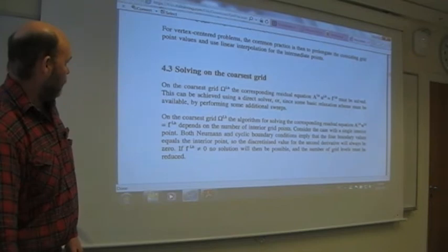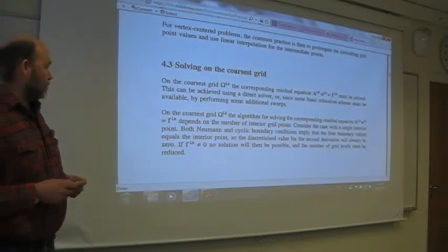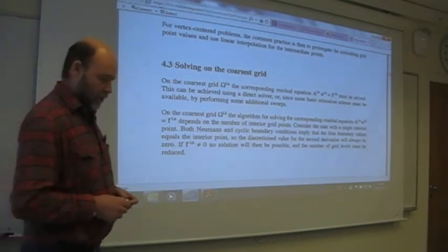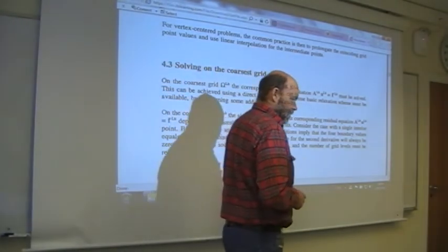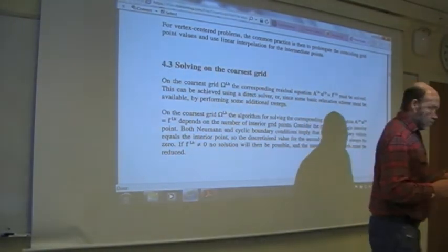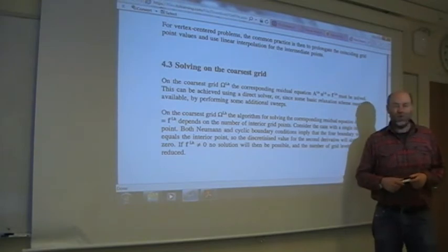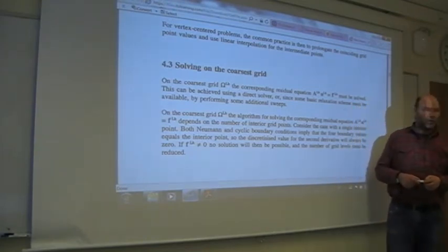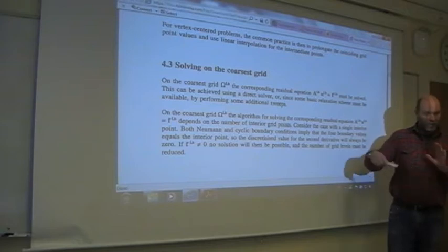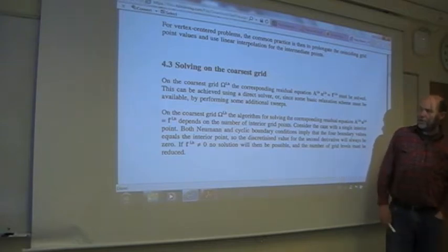So then it's a question of how to solve it on the coarsest mesh. If you are lucky, you have on the coarsest mesh just 1 single cell, 1 unknown. Of course, that one you solve directly. But depending on the geometry, the number of cells in X and Y direction, you risk having more than 1 cell on the coarsest mesh.